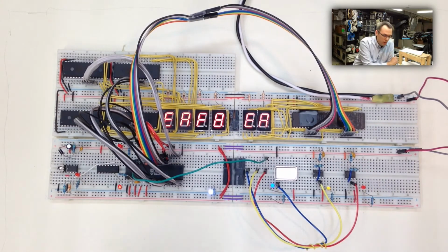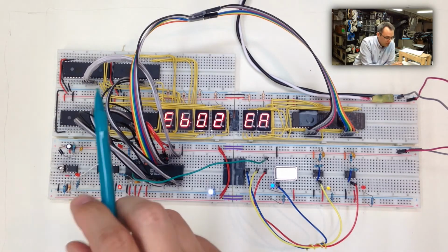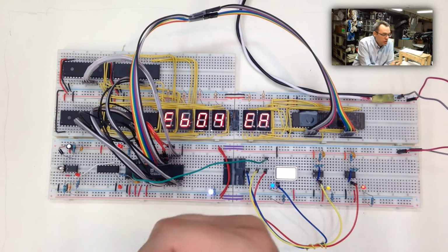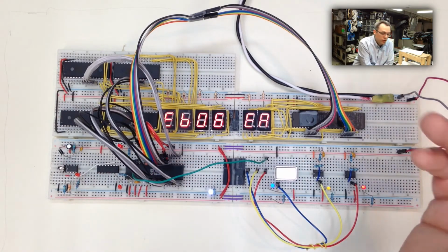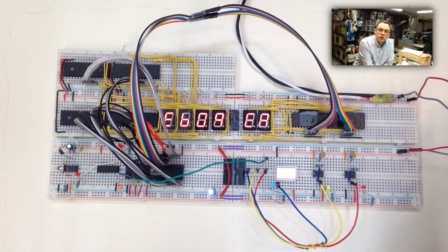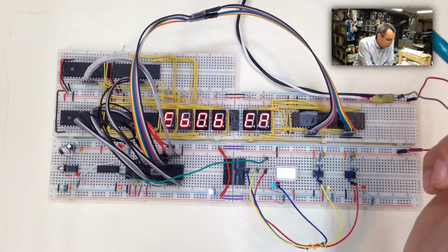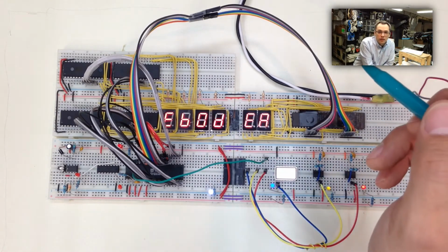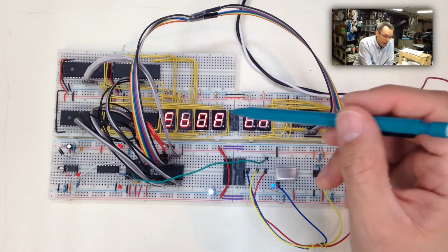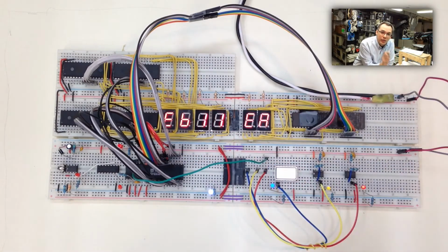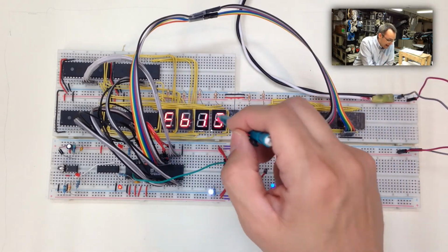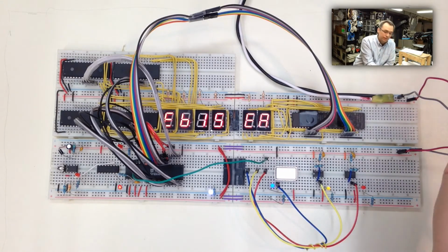Weird. Now let's explain what it's doing. The reason it did that is because we have the data bus hardwired to EA. When the CPU hits a reset vector or an NMI or an IRQ, it goes up to some of those high memory values to just fetch an address out of those memory values and unconditionally jump to what's in that memory value. Well, what is in the memory value of this computer at all times right now? EA. We have the data bus hardwired to EA. So it jumped to EA and started executing code.